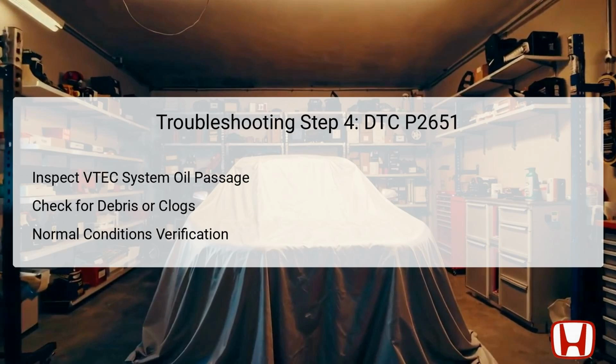To start, check for any debris or clogs, which can be potential sources of low oil pressure and are indicative of maintenance neglect. Thorough inspections can ensure that these passages are clear, allowing for adequate oil flow through the VTEC system. Normal conditions dictate that there should be no obstructions present in the passageways, ensuring efficient oil delivery.